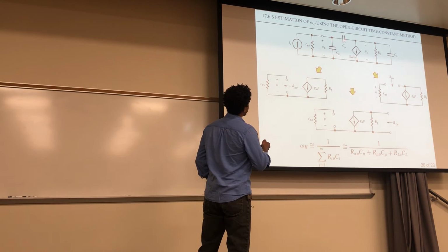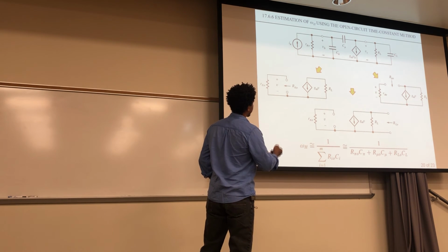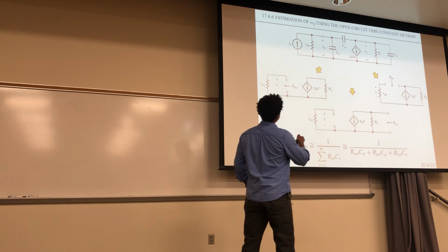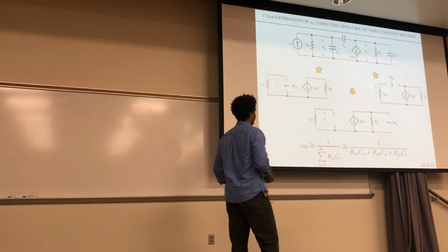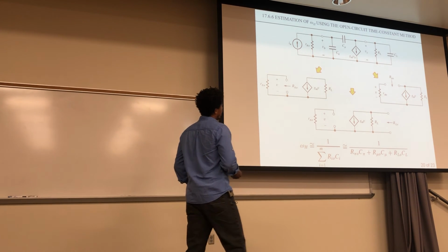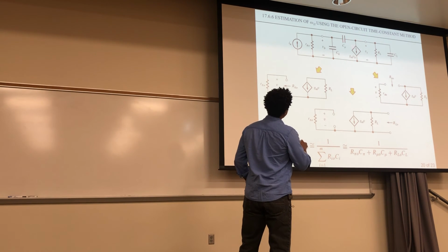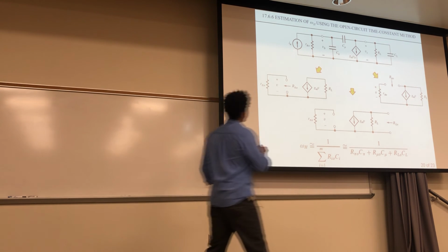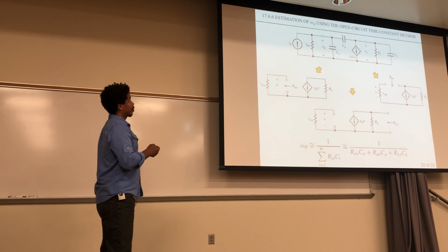For this one right here, this is now seen as the resistance looking in, R_LO, and these two become open. So this becomes open right here, and this just becomes open, just stays open right there. And you look at the resistance here. And for this one, C mu, you're looking at the resistance seen from this point, and this C pi stays open. So all you have here is just this resistor right here. And remember, the resistance of a current source is what?